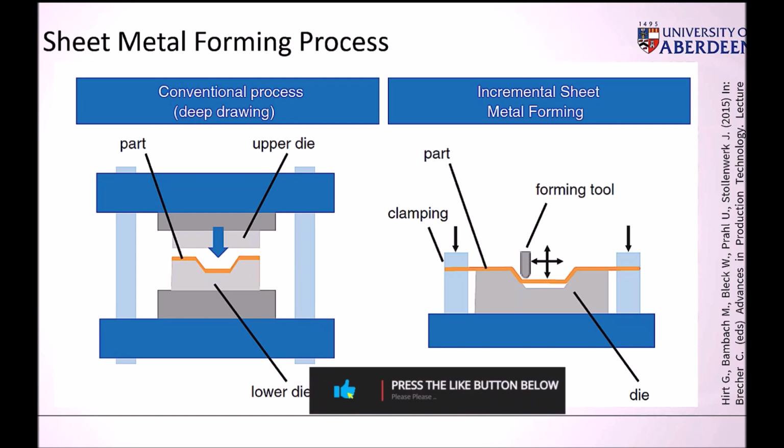So depending on the microstructure you have, we are able to account for those. You can model single and dual phase materials now. We can account for grain boundary effects if you already have quantified data. And if there is any loading history, for example residual stresses, then our models can account for that as well. From the fracture side, if you have a ductile failure, your voids start to nucleate and grow, and then they start to coalesce and form a bigger defect, right? So we are also able to account for that in our models.